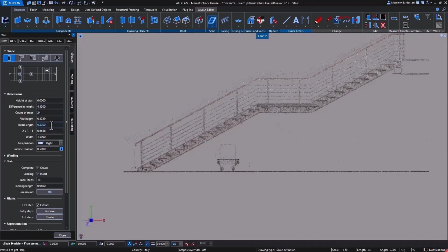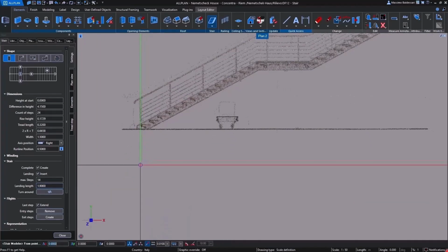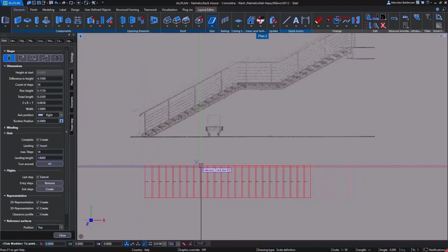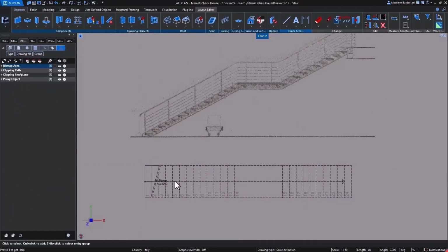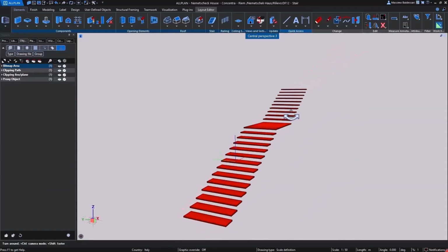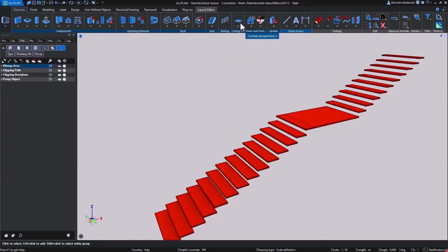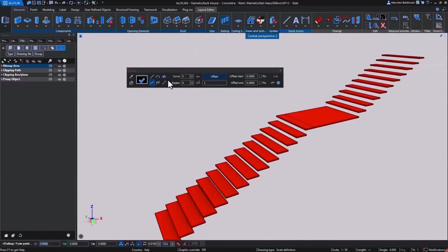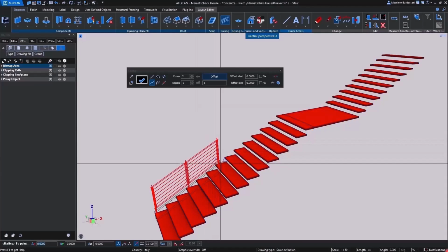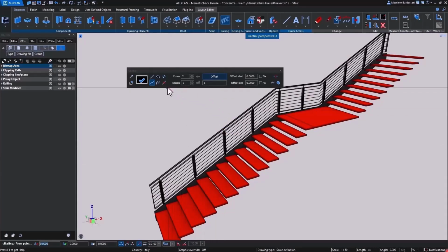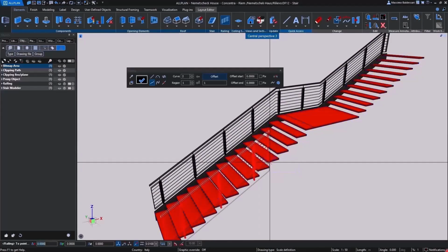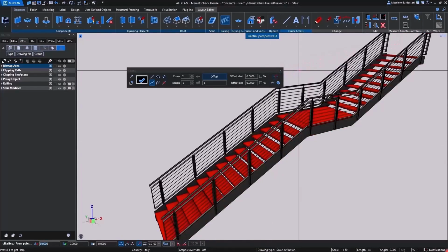All I really need to do is carefully define a few specific parameters, such as the total height of my staircase, the exact number of steps I need, and the overall length of my landing. Then I can simply align myself with the reference image shown above to very quickly and accurately recreate my entire staircase. So in a very short amount of time, I have successfully created my staircase, which as usual, I can now enrich with a whole series of intricate details, such as railings on both the left and right sides that accurately reflect the information coming directly from my point cloud data.